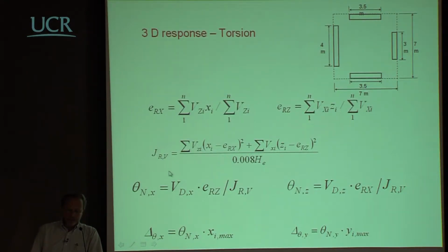Multiplying these two values, you can obtain the level of in-plane rotation that you need to have, and you can transform it into a displacement in both directions, in the x direction and in the y direction. And of course, you have to subtract this displacement from the displacement capacity that you want to use. So in the case of a rotation, you are essentially reducing the design displacement because you are using part of the displacement capacity to cope with the rotational demand.